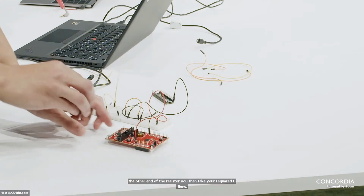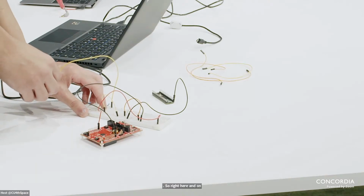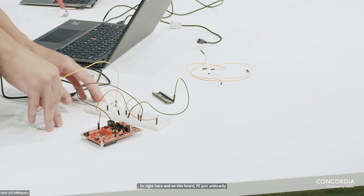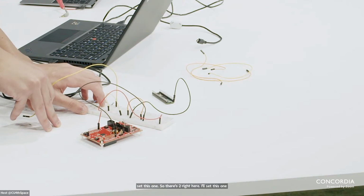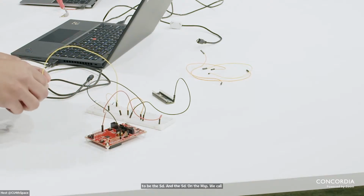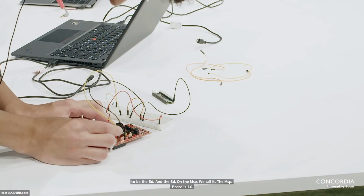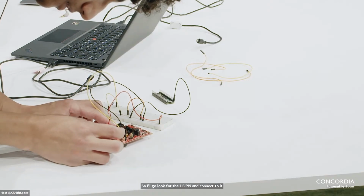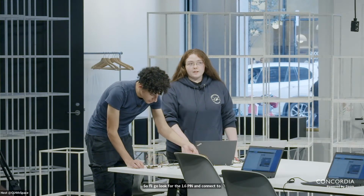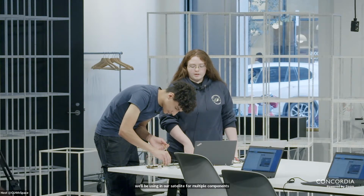So, right here. And on this board, I'll just arbitrarily set this one. So there's two right here. I'll set this one to be the SDA, and the SDA on this MSP, we call it the MSP board, is 1.6. So I'll go look for the 1.6 pin and connect to it. The MSP board is actually the kind of model of the board we'll be using in our satellite for multiple components. So that's why we brought this one today, to show you how we work with it in the lab.